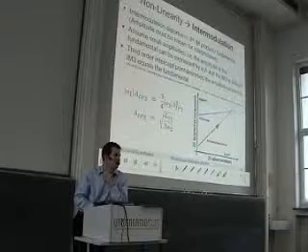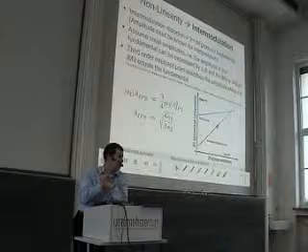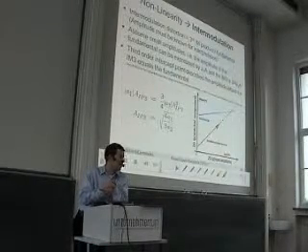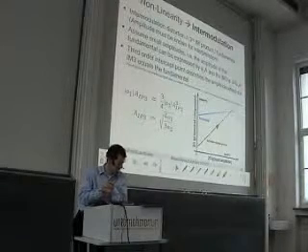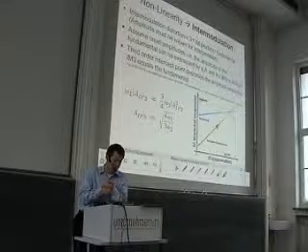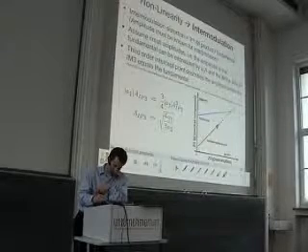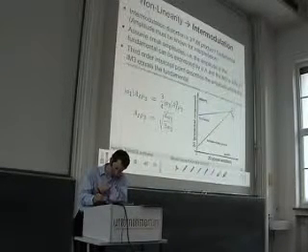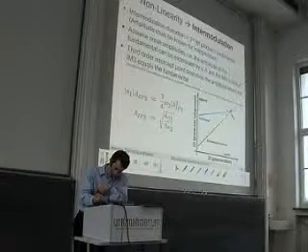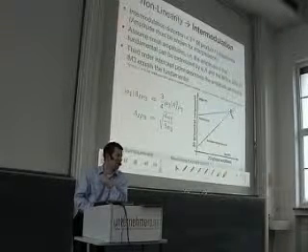You can do an extrapolation of these two lines. And at some point they have a crossing. And this crossing is then a measure people are using to quantify the non-linearity of the system. So by using this point here, this is what people call the third order intercept point.